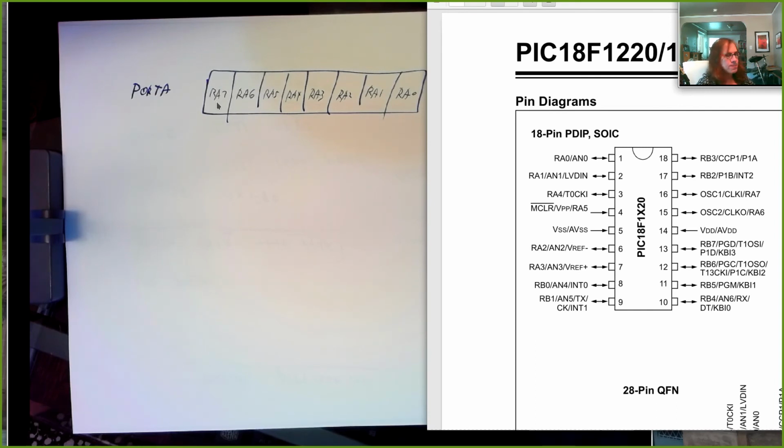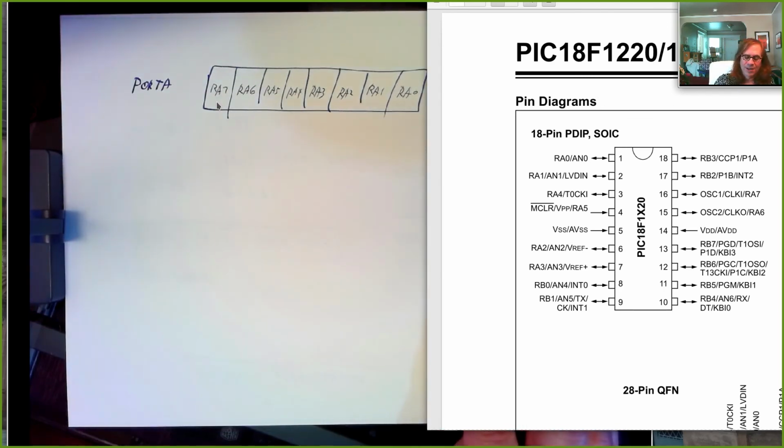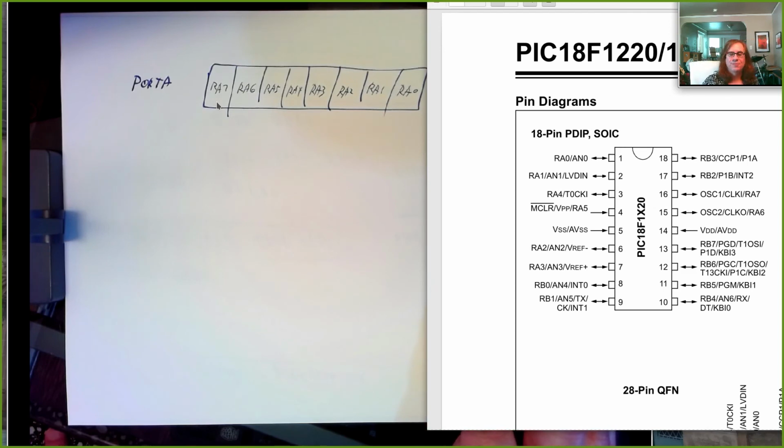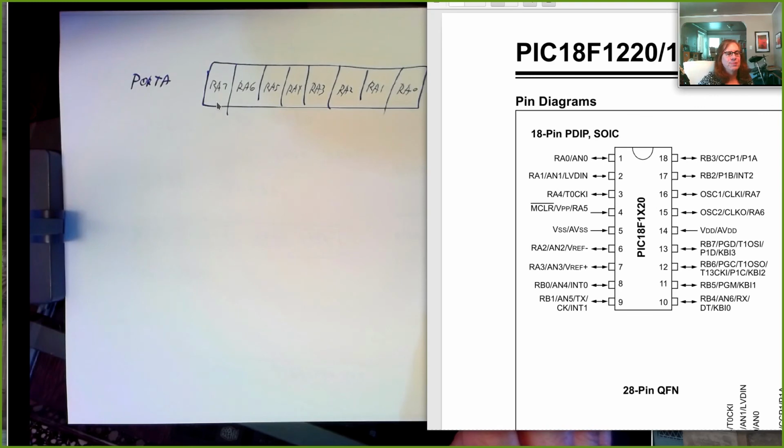Quick question. If for lab 1, when we put in the stimulators for RA0, would it also have the same effect if we used AN0? Probably, yeah. Could be an interesting new experiment, right? It should, because if you look at that include file that defines all of these things, RA0 is really just an abbreviation for 0, and RA1 is an abbreviation for 1. So AN0 would probably do the same thing because they're both on pin 1.